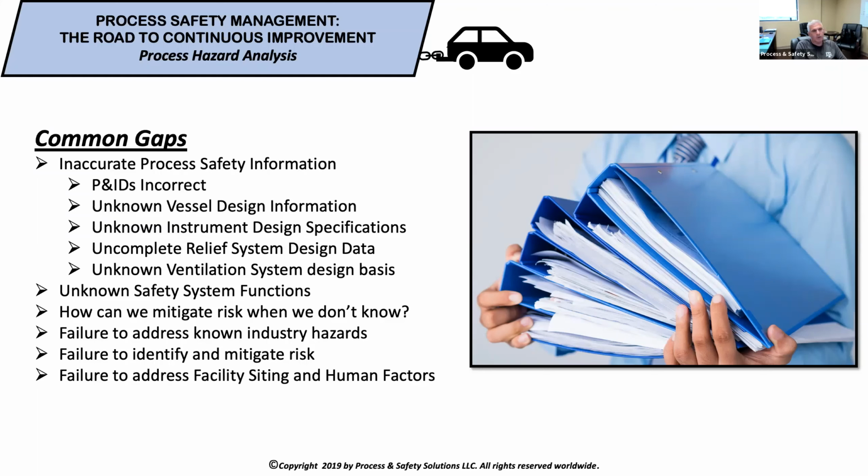What we're really looking for, in addition to those I just mentioned, is things like fatigue, work hours, and being able to get to certain parts of the process. For example, do they have to climb a ladder to close a valve? Do they have four screens of active alarms that are always on? Do they have to page through multiple pages on the screen in order to address an alarm or a failure of some sort? Those are the sorts of things that we're looking for in human factors.